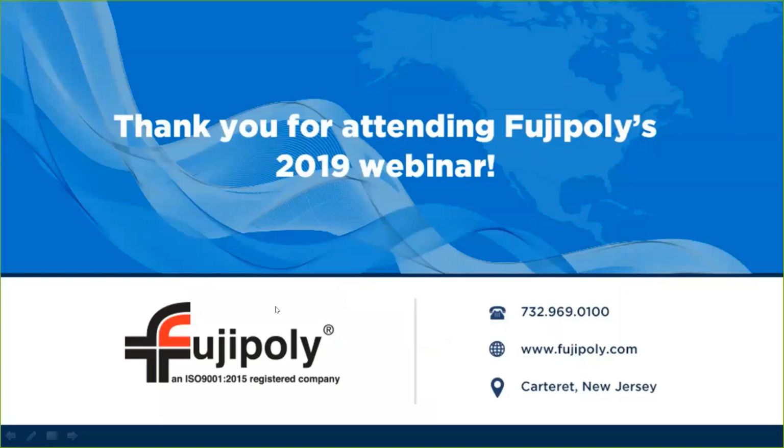Another question: is the putty material already cured or does it need to be cured after application? There is no post-curing of this putty type material. It comes in sheet form already as cross-linked as it's going to be, and there's no added process for the customer. Okay, another question: what is the shelf life on putty material? Our putty has a shelf life of 5 years from date of shipment.